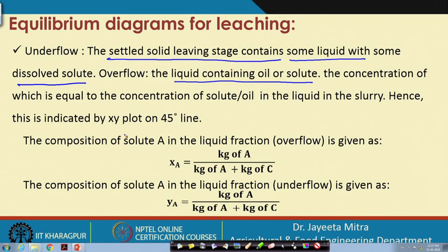Hence, this is indicated by an xy plot on a 45-degree line. If we plot this concentration, suppose I denote the concentration of solute in the overflow by x A, and the concentration of solute in the underflow solvent by y A, this will follow a 45-degree line. We have that diagram, maybe in the next slide we will show you.